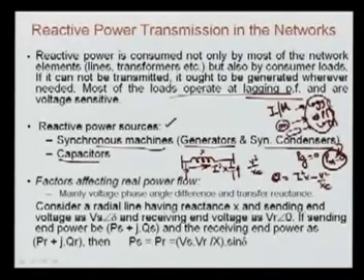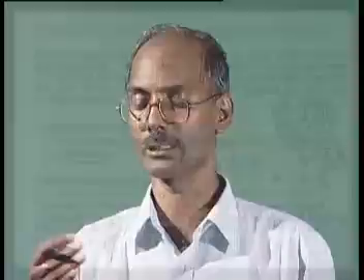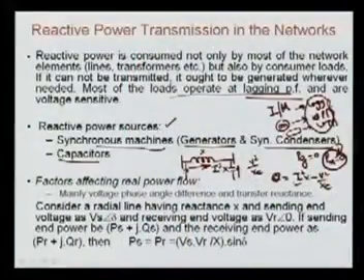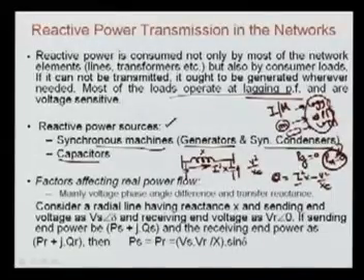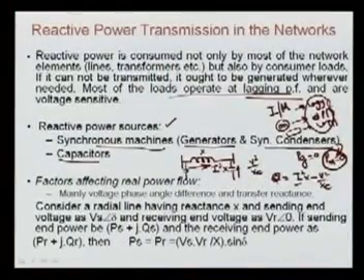If I is less, meaning loading is less, then this component may be less than the other, because V is normally the rated voltage and the variation is very small, but I can be from 0 to its critical loading. So this line can generate, especially when the system is lightly loaded, for example sometimes in monsoon seasons or in off peak hours, from midnight onwards when the loading of the system is reduced. So this line can generate reactive power.